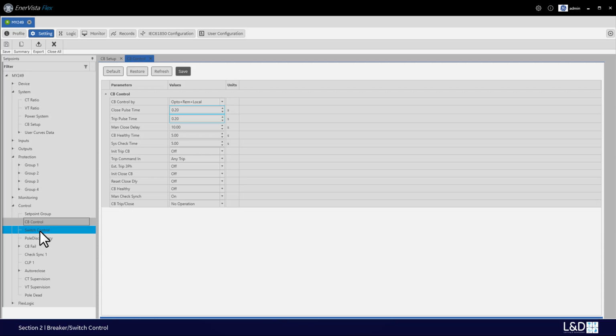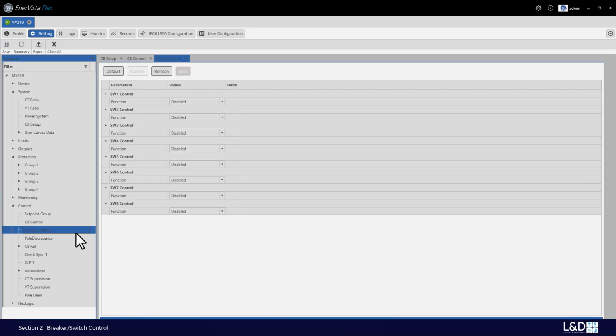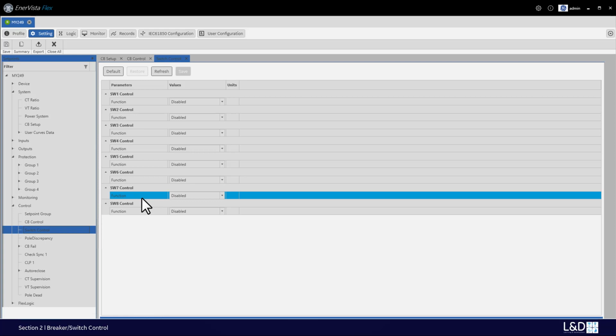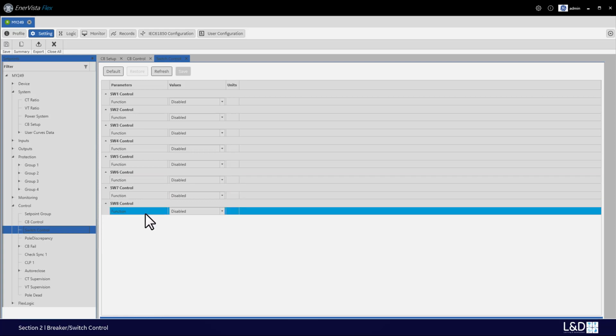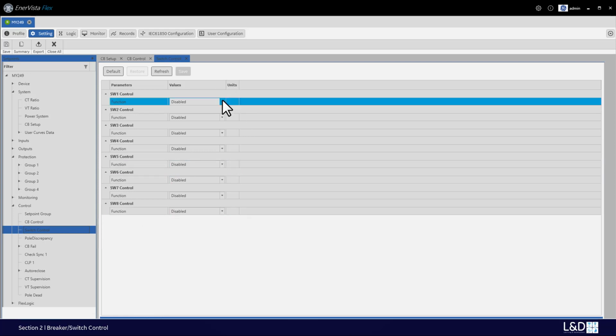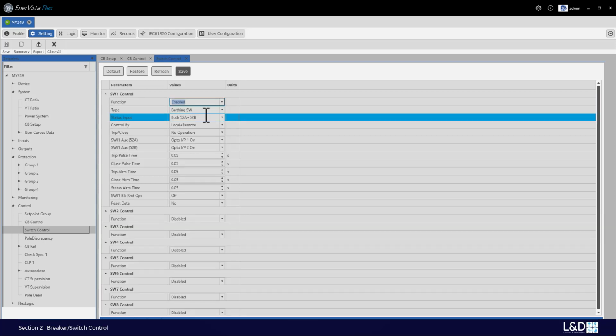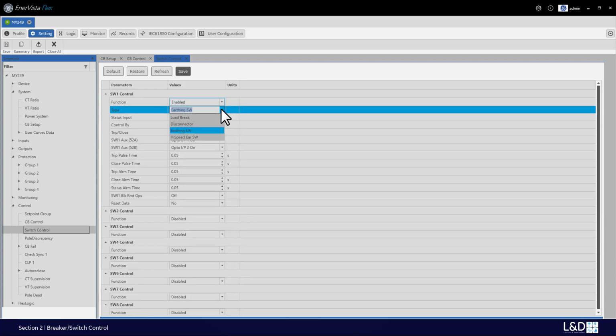P40AE-105 enhanced support the switch status and control for up to 8 switchgear elements. This device is able to monitor the status and control up to 8 switches. The type of the switch options are load break, disconnector, earthing switch, and high-speed earthing switch.